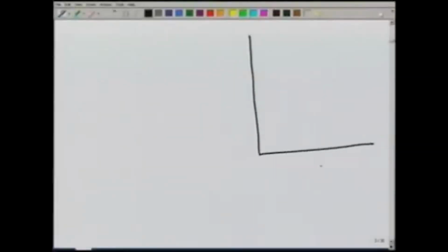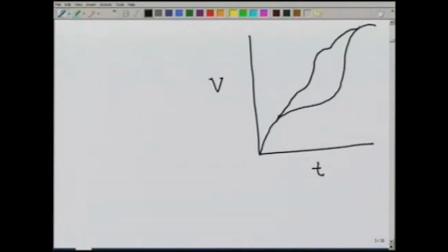Now, let us look at what happens if the demand is variable. Accumulated volume V versus time t. So, we again have this mass curve and then we can plot the demand curve on this, which is now variable. So, it may look like this, and again the philosophy is the same, that we take whatever is the maximum difference between these two curves.